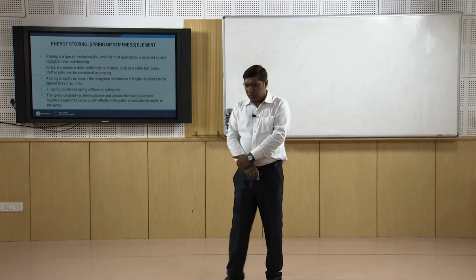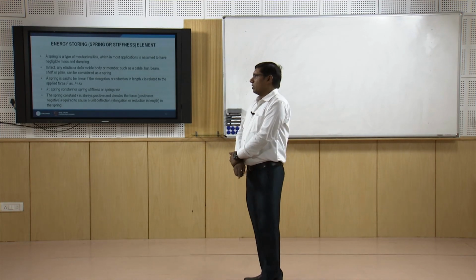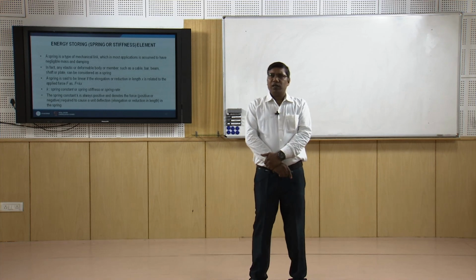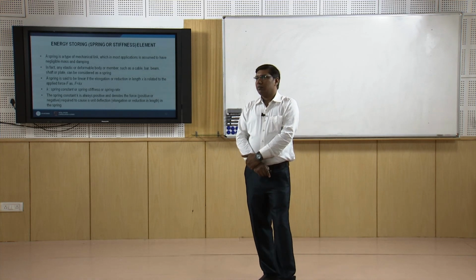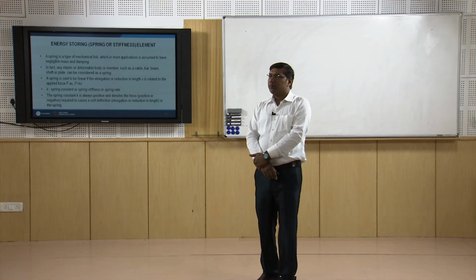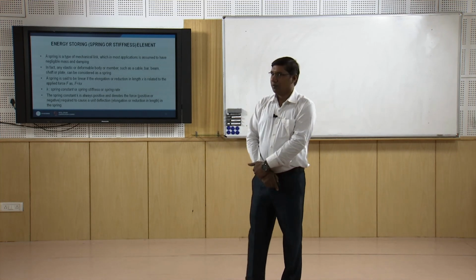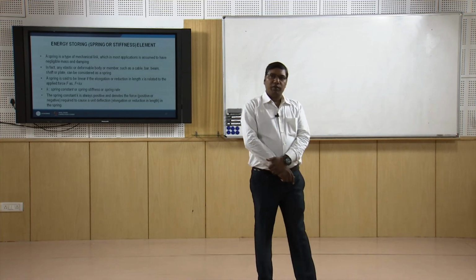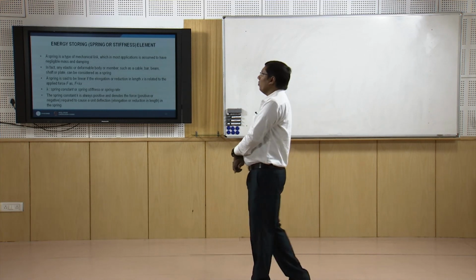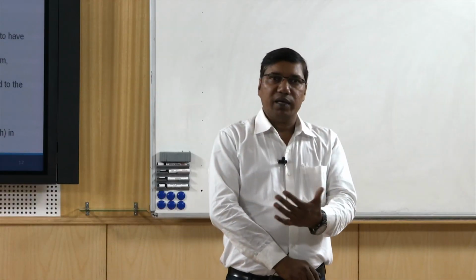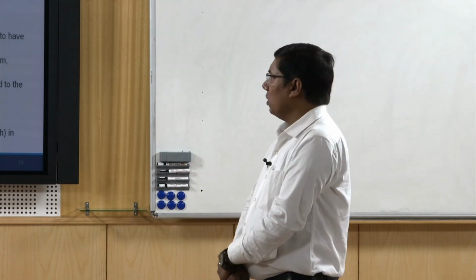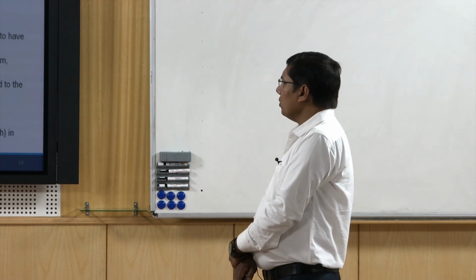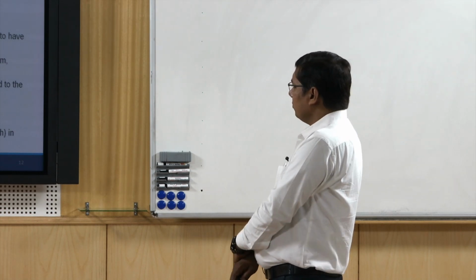Now we will discuss some basic elements for vibration modeling. Mass, stiffness and damping are the 3 basic elements. They have certain roles. For example, we have the stiffness or spring property. They are the energy storing elements. During the vibration of the system, they store energy as potential energy, and they can give back that energy for the vibration of the mass.